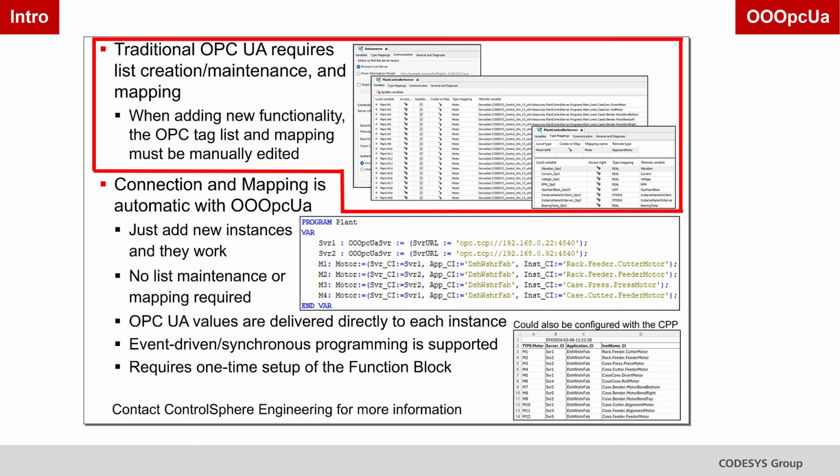In traditional PLC programming, we complete our code, then proceed with a number of post-processes necessary to complete the design, such as populating the alarm list, the I/O list, the log list, the persistence list, and so on and so forth. These lists take a great deal of effort and tend to be a significant source of errors, and need further effort to update any time the design is modified. It's common to create Excel or Python macros to automate some of this list creation process. You export the data from CODESYS, run the automation to extract the necessary data and format the results, then read the file back into CODESYS.